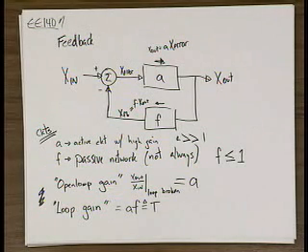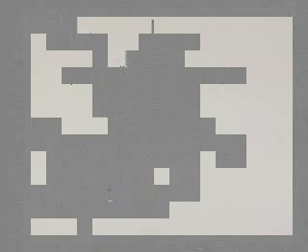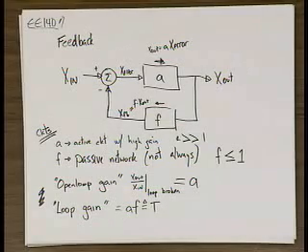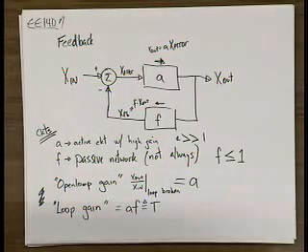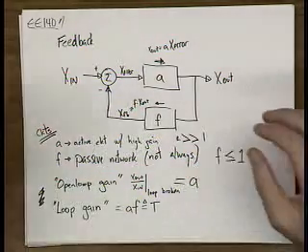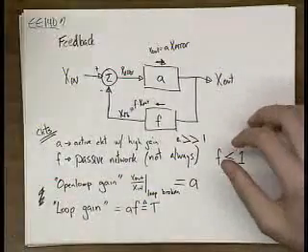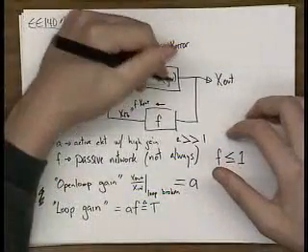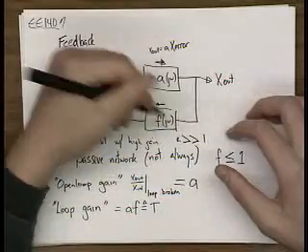So the output instantaneously is fed back to the input. There's no delays. Well, okay, so let's not talk about delays in the discrete sense. Let's talk about delays. What does a delay manifest itself as? A delay manifests itself as a frequency-dependent gain, right? It could be a phase shift. So in reality, all these things are frequency-dependent. A is frequency-dependent. J omega is frequency-dependent.